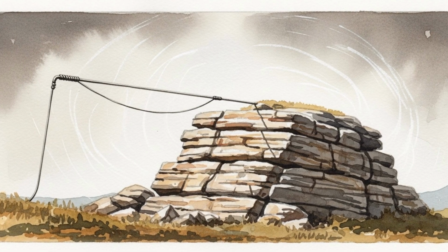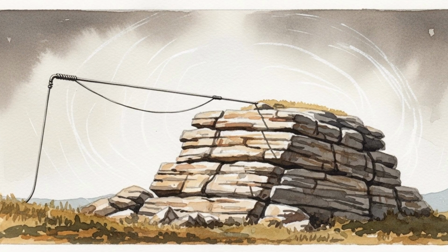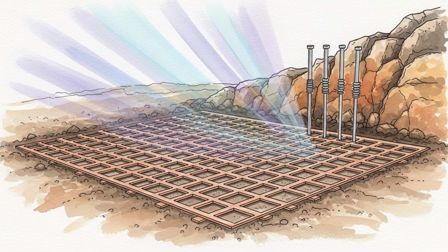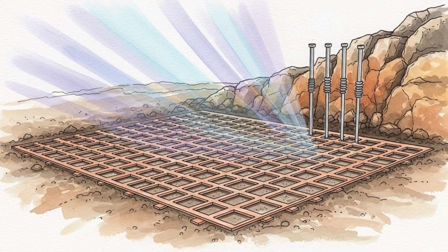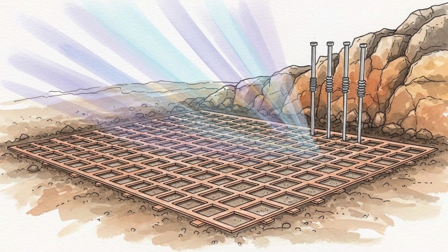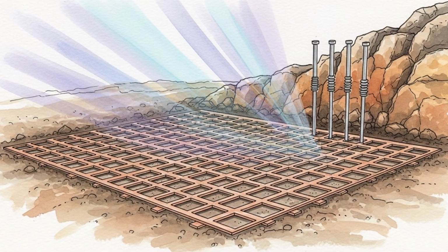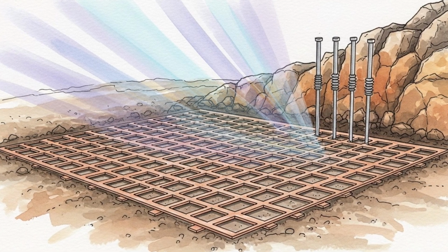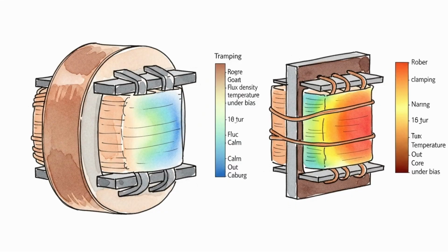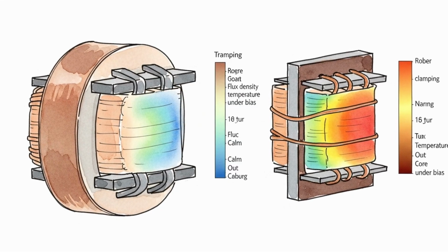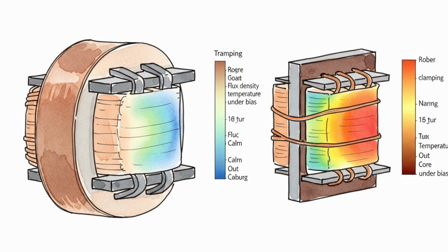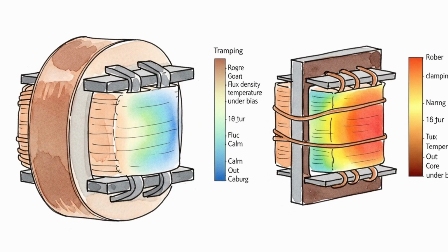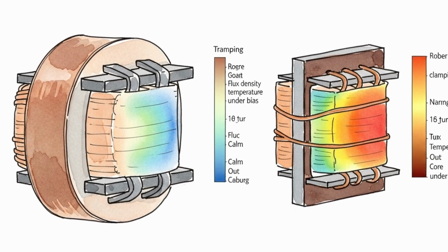Attitude and orbit control are affected by both environment and operations. Star trackers can lose contrast due to increased background and particle hits. Guidance can fall back to coarse sensors. Reaction wheels and control moment gyros see more duty if drag torques increase at low altitudes. Thruster budgets must cover extra aerodynamic torque and more frequent orbit corrections. Safe mode attitudes often increase cross-section and drag. Teams plan safe mode orientations that balance power, thermal limits, communications, and drag exposure.